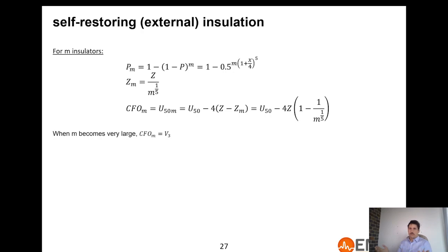But you can use reasonable assumptions and cut the line in pieces. And so then basically you will calculate several characteristics. The characteristics you will need eventually, I can tell you now, are the CFO and the BSL. So you can calculate the CFO and the BSL for several sections of lines and equipment, and have all those saved somewhere for your analysis. And so if you have an entire line with no surge arresters, that's how you do.